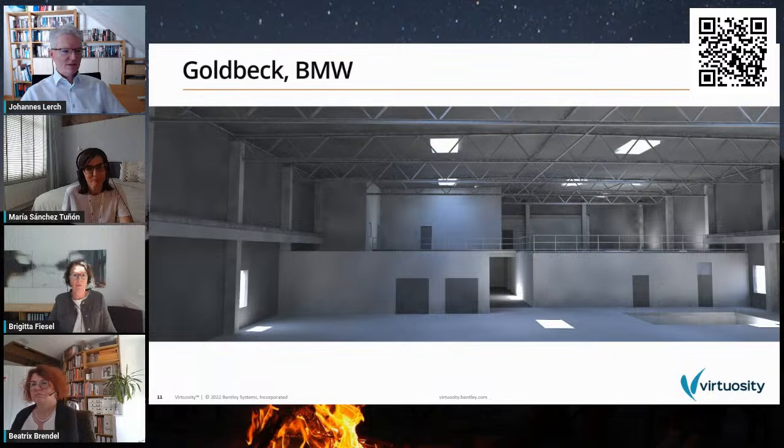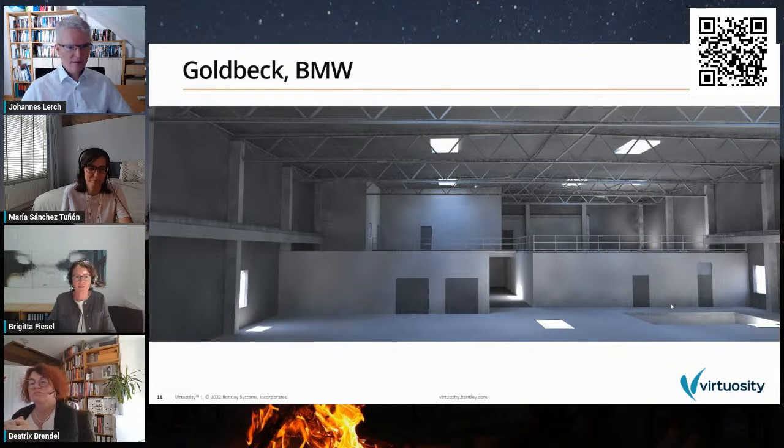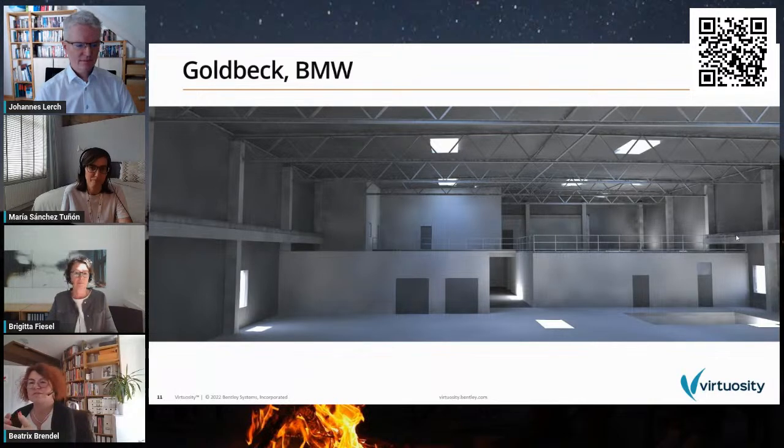Yes, we use the point clouds if we have buildings that are difficult to measure, where they are not designed with rectangles, and so the point clouds help us to get a really good as-built model. As we saw on the last slide, there was a technical drawing, but it was an old one. It was drawn by hand, and so you had to look into that and put it together with the point clouds.